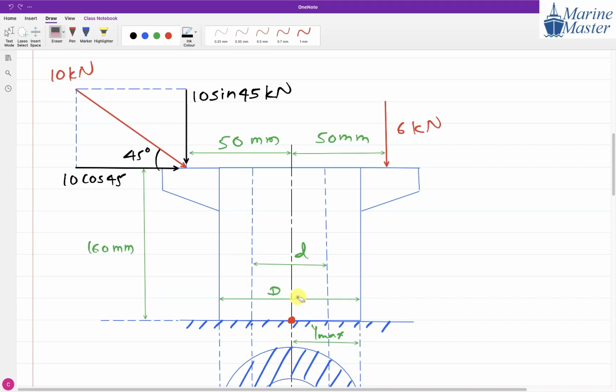Now everyone, if the force is going to pass through the center line, no moment due to that force. Now here in this case, don't consider sagging and hogging. It leads to confusion. Here the story of sagging and hogging gets finished. How to take a moment? We will assume clockwise as positive and anti-clockwise as negative. In this case, the story will become very, very simple. Don't consider sagging and hogging in this scenario.